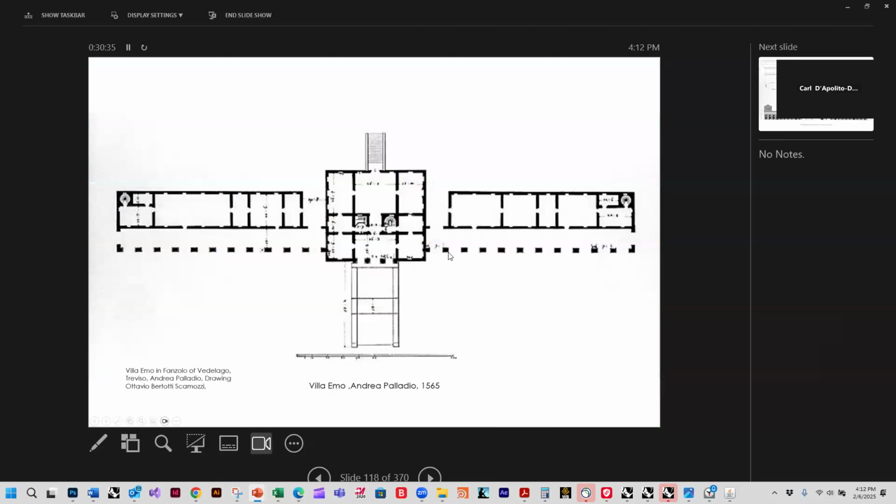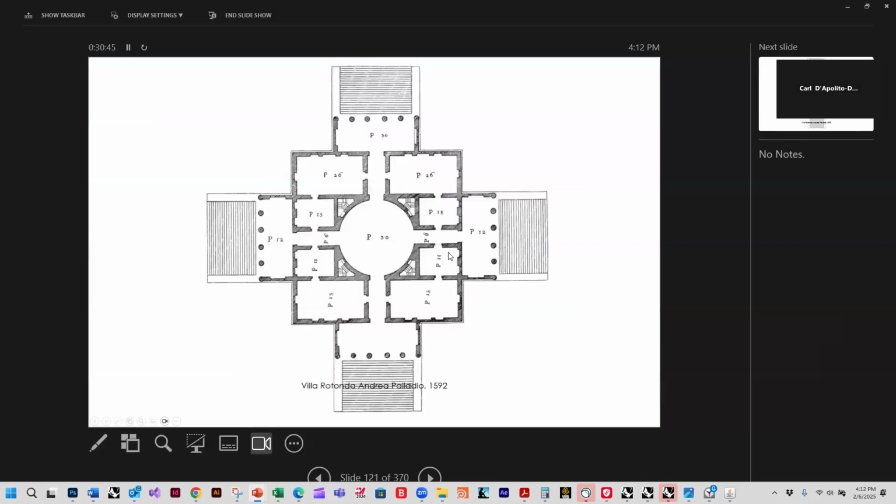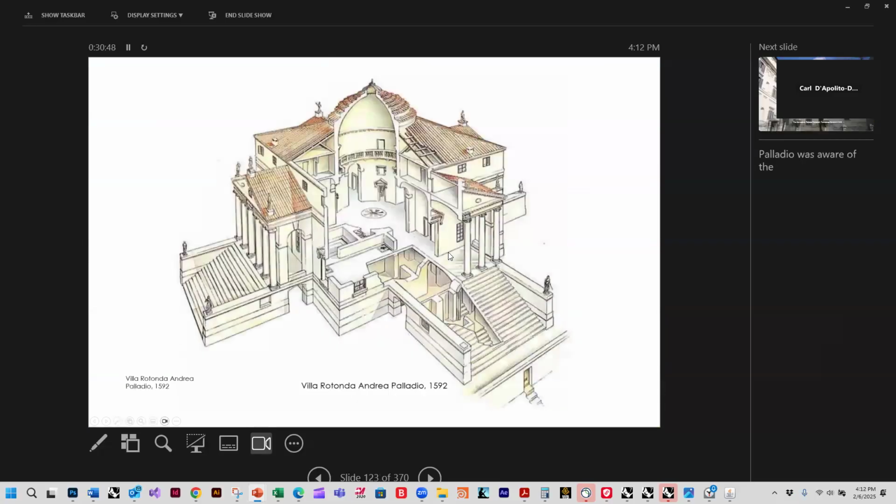And the Villa Rotunda is the same. Okay, it has a big old cold basement, and it has vents in the floors. I don't know if I have a photo of them. Yeah, look. Right? Look at that. The big hole in the floor. So the air cools down in the cold basement with the stone next to the earth, and that's then pulled through the building by the tall dome, where the hot air creates a temperature gradient.